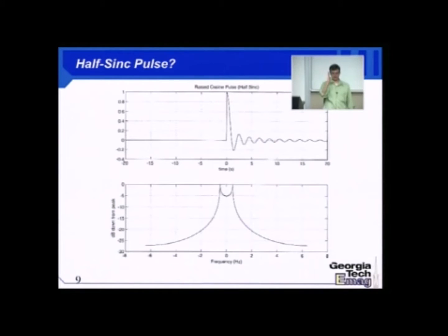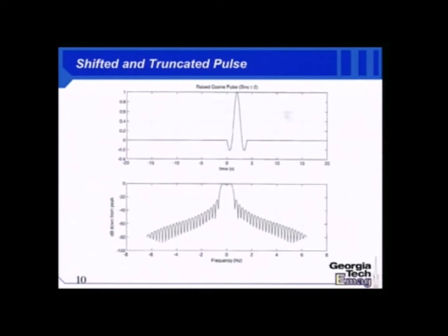which is basically 4 times outside the bandwidth. So if I took the center frequency of this pulse, I put it on an RF carrier, and I moved to the edge of my band, 4 times that distance, I'm still only 20 dB down in signal energy. This is a terrible way to send information. But okay, let's tolerate some latency. Let's take that sinc pulse and shift it over. Oh, that's nice. There we go.